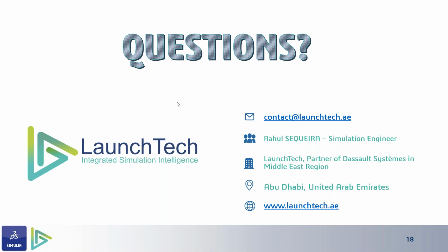I have another question asking, can you please provide more info about shape memory alloys? It's a good question. You can do it, but you also need to consider the implementation of the shape memory alloy constitutive model, and you can even do that using the subroutines UMAT or in the form of Fortran code. So that is possible. If you wish to know more about how you can do it with shape memory alloys, I would recommend you drop an email so that we could support you with that query.